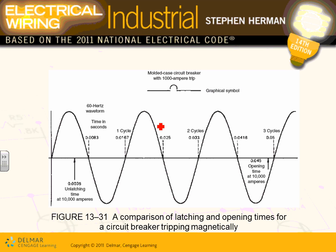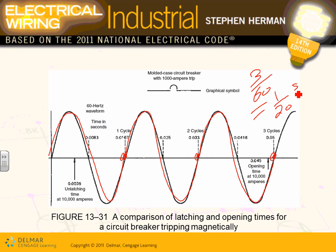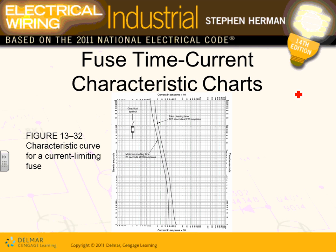If you have a circuit breaker, it is supposed to open within 3 cycles. So here's 1 cycle, 2 cycles, and 3 cycles. And 3 cycles, Karen, is 1/20th of a second, right? You take 3 cycles divided by 60, that gets you 1/20th of a second. If it doesn't open in that time, most of the equipment will burn. So that's the opening characteristic.